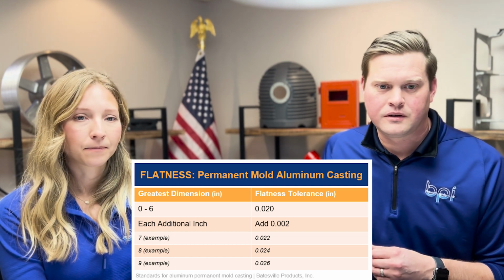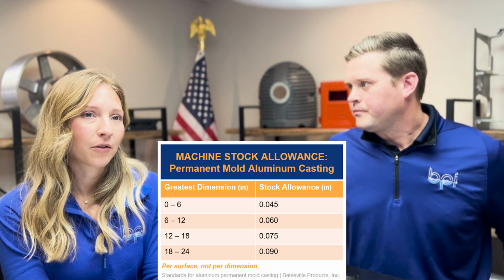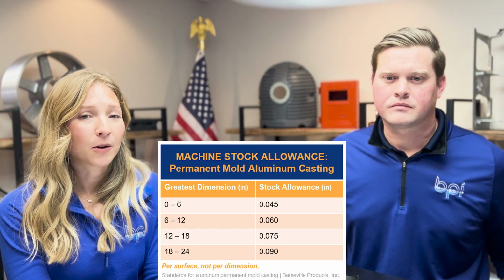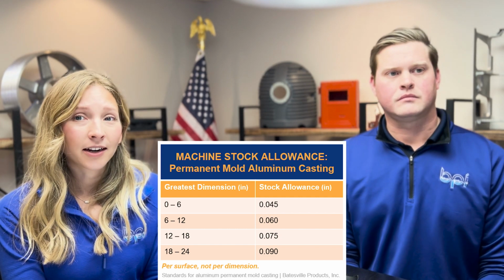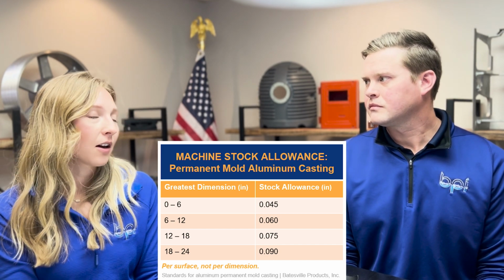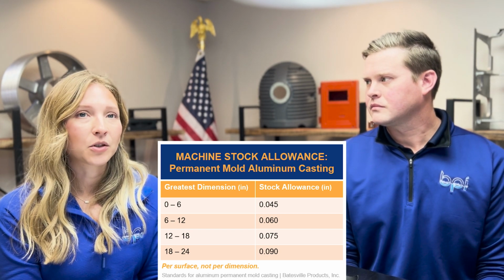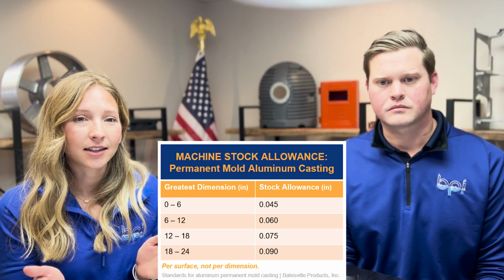So. Yeah. Machine stock tolerance. In general, as a rule of thumb, I would say permanent mold falls in the middle, where with sand casting you're going to need a little bit more stock on there to allow for machining, whereas you're going to get a little tighter tolerance on permanent mold when it comes to near net shape castings.